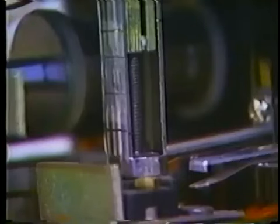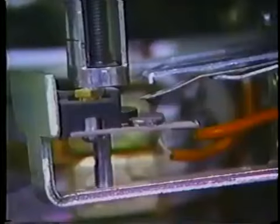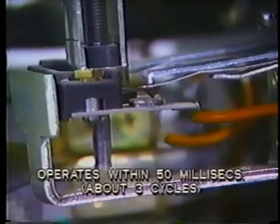In this case, the electromagnet pulls the plunger up against the force of gravity. Again, the pickup level can be preset by adjusting taps and also by adjusting the position of the core. When current exceeds the pickup level, the instantaneous relay will operate within about 50 milliseconds, that's about 3 cycles, and energize the tripping circuit to open its associated breakers.